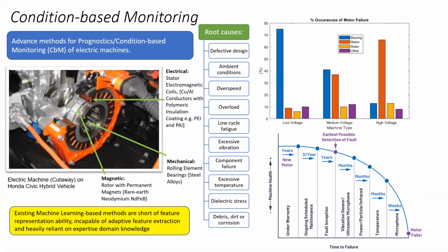There are three major maintenance approaches to consider, the first being reactive, when machines are simply run to the point of failure before any maintenance action is initiated. The second is preventive, which involves scheduling regular checks on the performance of a machine to replace components before they reach the stage of severe degradation. This option improves upon the previous by eliminating the occurrence of catastrophic failures, but the main drawback is determining the most optimal time to perform the scheduled maintenance in order to get the maximum usable life from the component.